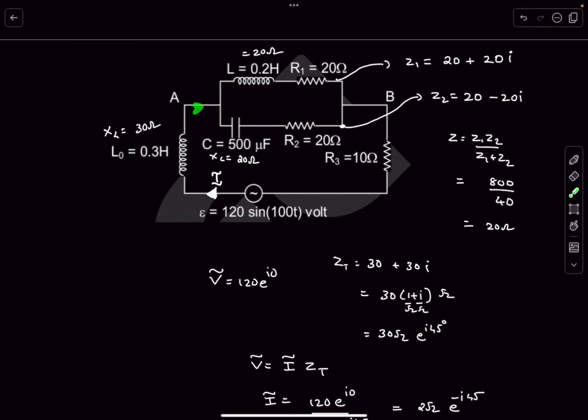Okay, so let's assume for a second this is a DC circuit and we have two resistances in parallel. As they are in parallel, the potential drop across these two branches is the same. So we can say I1 R1 equals I2 R2. Or in other words, we can say that I into R is a constant. The current divides in the inverse ratio of the resistance, basically.